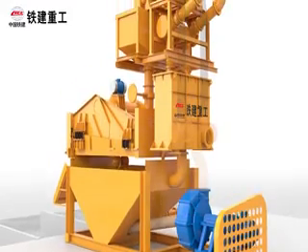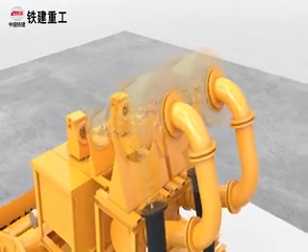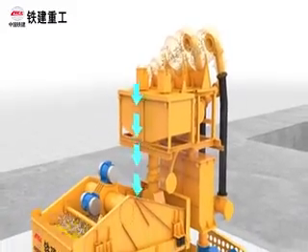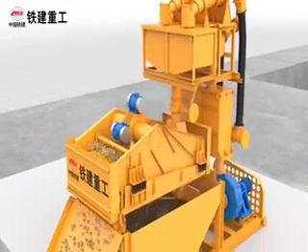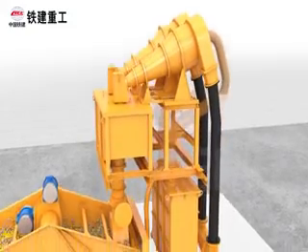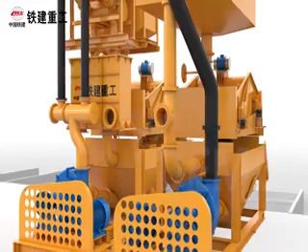Secondary screening. The pump boosts the slurry in the storage tank B to primary cyclone module. After the treatment, the underflow slurry enters the lower vibrating screen for dewatering, and particles above 74 micrometers fall into the muck pit for storage. The overflow slurry enters the storage tank C through the bottom tank.